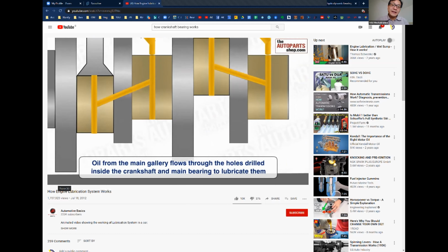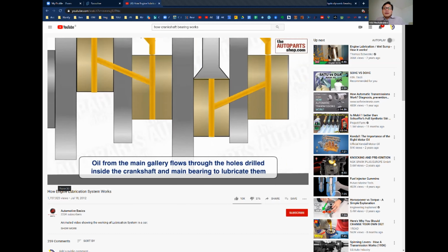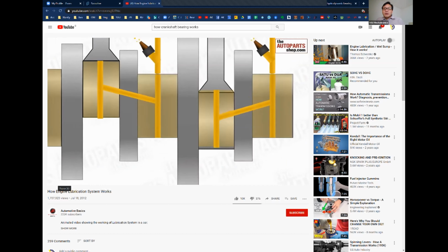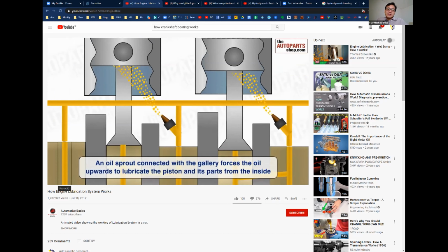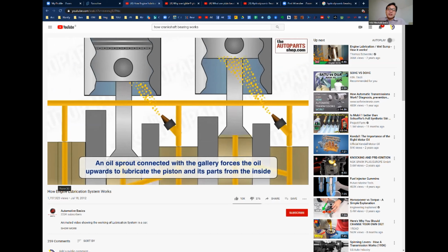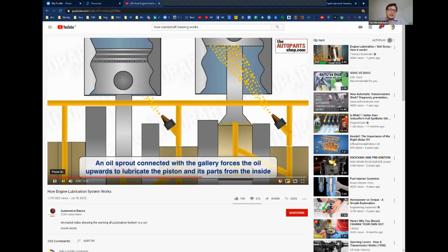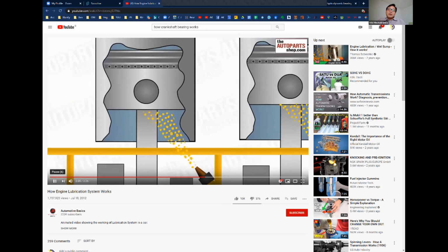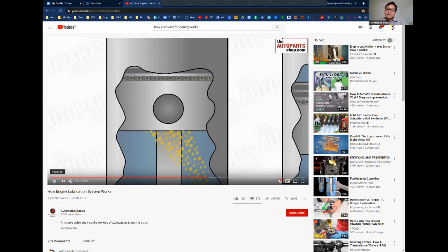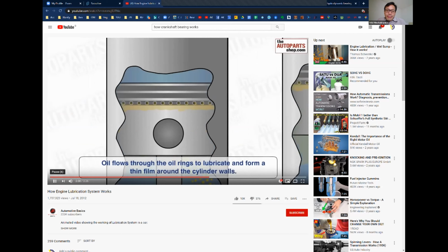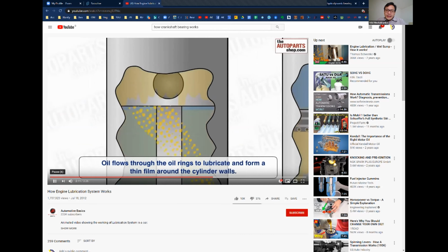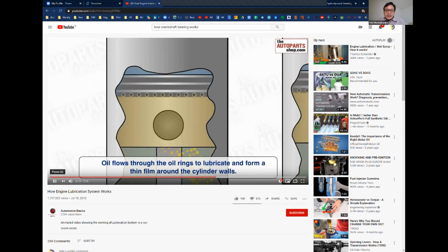And so the shaft actually floats on liquid, on oil. Now you understand why the oil is very crucial, right? If your engine runs even a minute or 2 minutes without oil, forget it, it's trash. It also lubricates the cylinder walls.